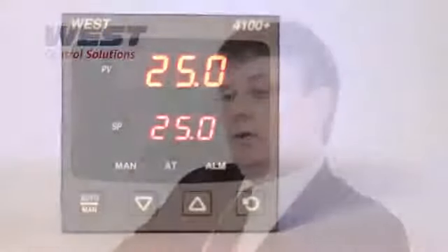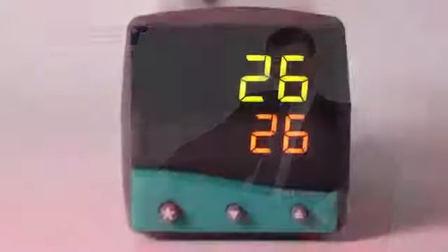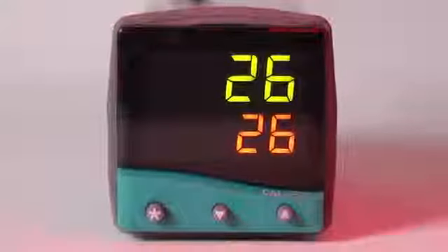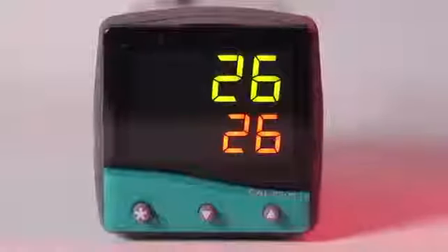In our CAL product range, this type of alarm is referred to as a full-scale alarm. It is available on all instrument types, including indicators, controllers, and the more specialist types of controllers such as profilers and limit controllers. In addition, most of the controllers will also feature a deviation alarm or a band alarm that works relative to the set point rather than to an absolute value.